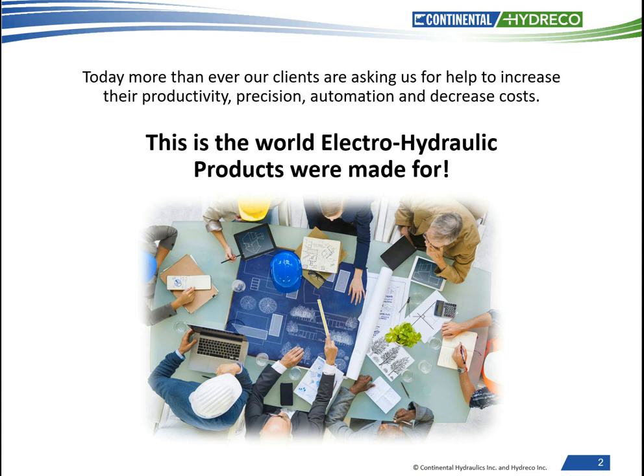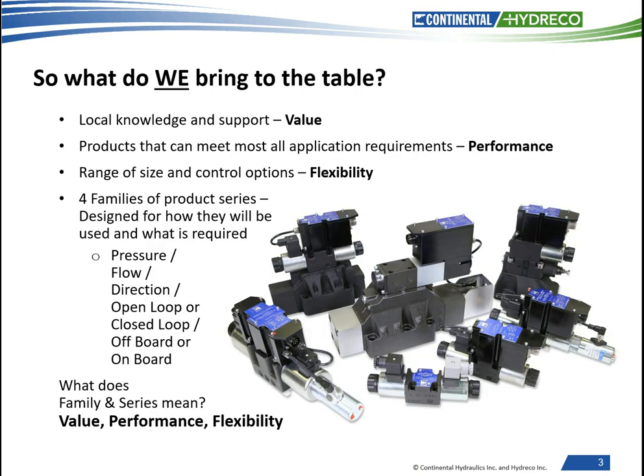Know the load. Will the load be the same and react the same each and every time, or will it vary? What are the ambient conditions? Mechanical stiffnesses? Is this an all-new system, or must you use existing system components and make it function better? The bottom line, proportional electrohydraulics is a system, not a component.